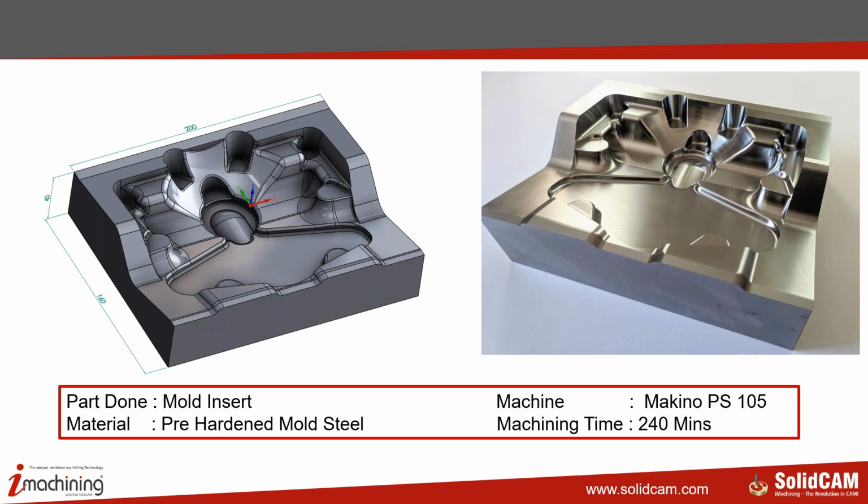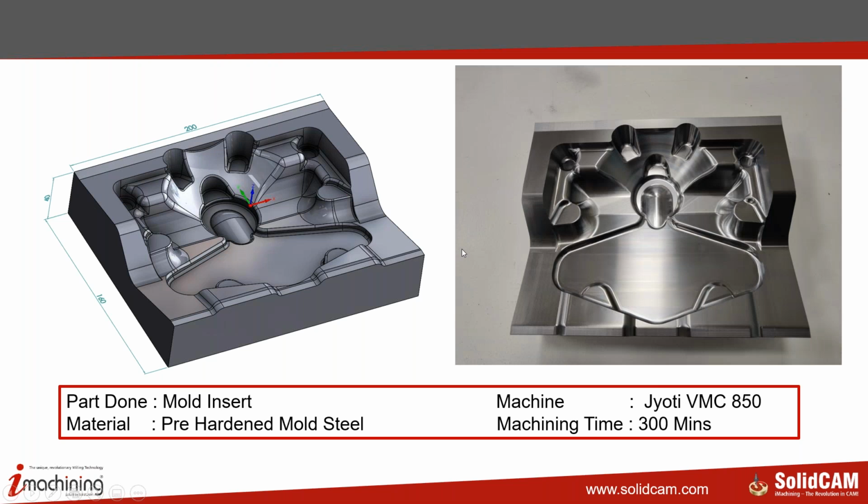And you can look at the surface quality that was achieved. This is pure milling. No hand finishing has been done on this part. Now, this was a high-end machine like a Makino. We talk about an Indian machine, Jyoti VMC 850. The same part was done in 300 minutes, obviously because it doesn't have those kinds of high parameters like the Makino. But you can look at the surface quality generated by this machining using our HSM and Turbo HSM functionality. Again, this is not touched by hand. This is purely as machined on the machine.